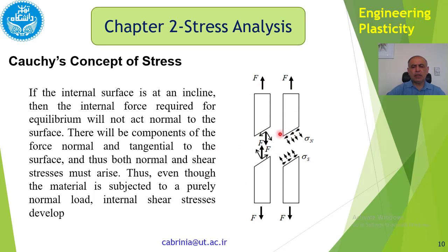Of course, I explained this in the introduction because at that time I wanted to show you how shear or slip occurs. But here we are not talking about the slip or shear, we are just talking about the component of stress. So for equilibrium, to maintain equilibrium, we have to have components of stresses like that, so that the resolved force will be in this direction. Even though the material is subjected to a purely normal load, internal shear stresses develop. So that's why we have shear stresses here.